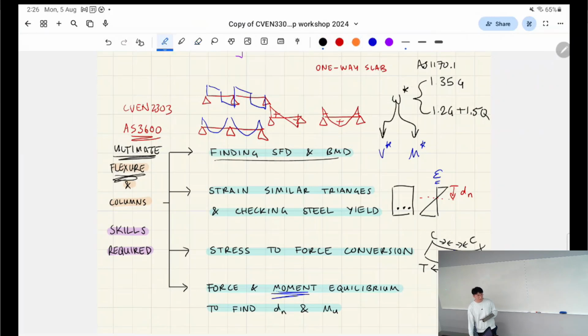Okay. So an important thing to note about the ultimate moment, or the point where the beam's basically failed, is it's always defined by the same point, and it's based on the compressive strain. What defines the ultimate moment is when the strain on the outermost compressive fiber reaches 0.003. Say that right? 0.003. Just keep that in mind. You'll need this for almost every flexural or column question, just this information alone. So, is anyone familiar with similar triangles? That's my next point here.